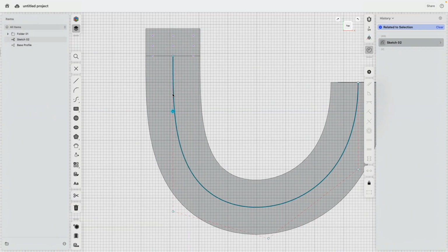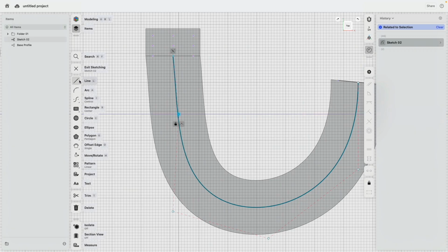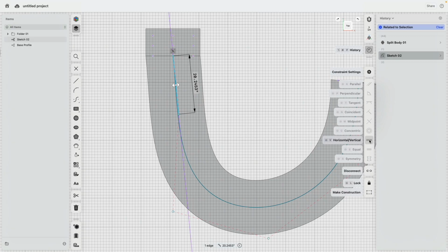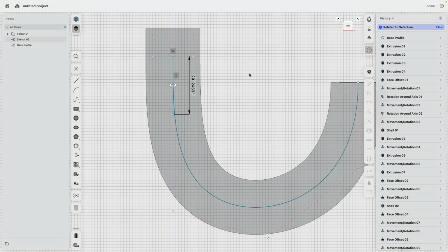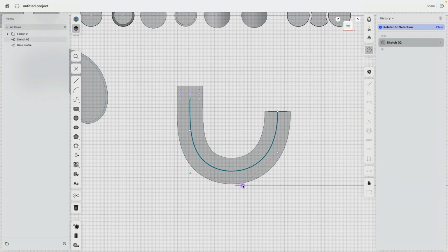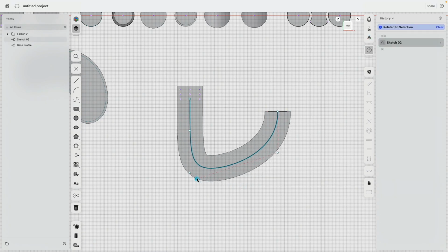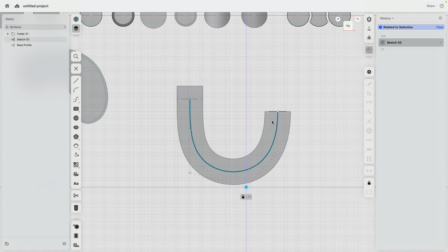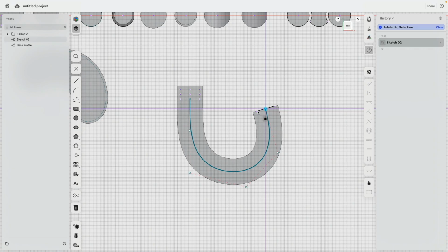And I simply here use, now you could say the grid or actually the snapping. If that doesn't work for you, you can use a very simple trick: draw a line between the first and the second point, and then make this horizontal or vertical. There we are. We can delete this if you don't need it anymore. Yeah, very good. So I can move this around to make this, and this is pinched right here. That's not nice. I can just maybe make it like this. And this one, let's make this angled.